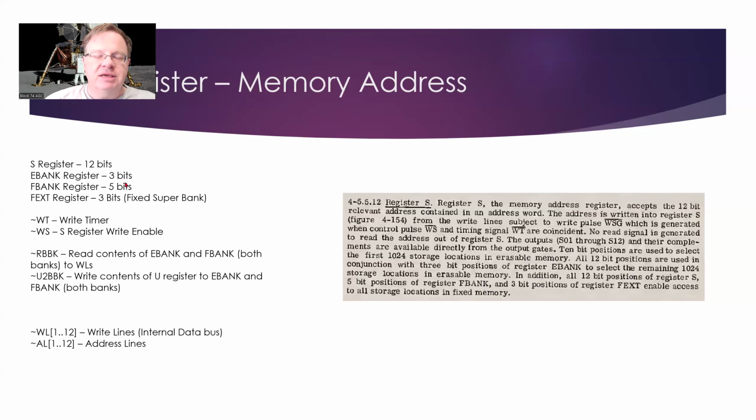And then, of course, as the guidance computer got more and more complex and the programs got more complex, they found that this 5-bit fixed bank register wasn't sufficient. So they actually had to create an extended, or what they call the fixed super bank. That's another 3 bits in order to add additional banks of memory that can be swapped in and out in order to read instructions from.